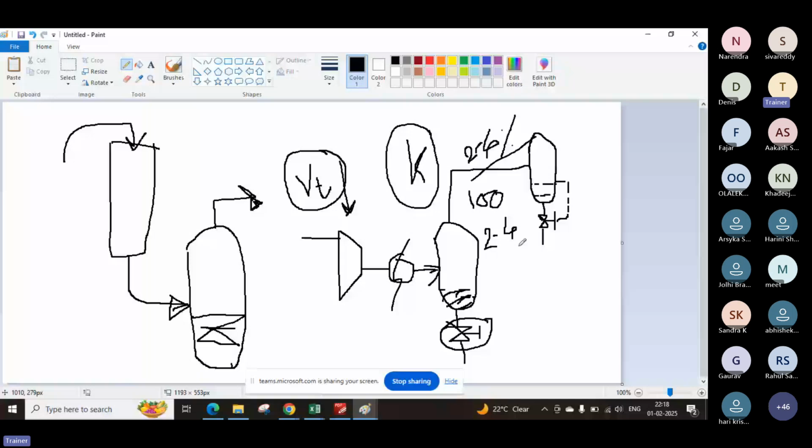If that is after the third stage of compressor and you are pretty confident that there is no chance of condensation in this zone, then you can omit that. But generally, whenever you have any ISBL or OSBL coming, you need to have a separator at the inlet of any phase or any fluid coming across the borders with a blocking mechanism and all.